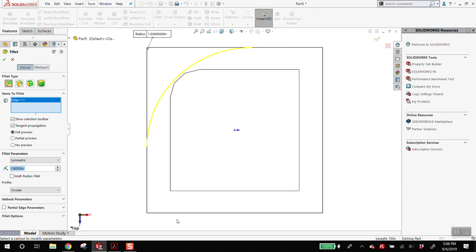If I were tracing this, to me, this is a design feature. I mean, this is so nuanced, and to each their own. People may disagree with me. I would probably build this in. I would probably fillet this, because to me, this is on the foot, it's on the base. Yeah, you could argue this is a design feature, but it's kind of like a secondary thought. I would build a hard edge for this down here. This would be part of my sketch. I would sketch out an arc. That's somewhat nuanced, and again, to each their own. But I would say best practice, this would be in the master sketch.